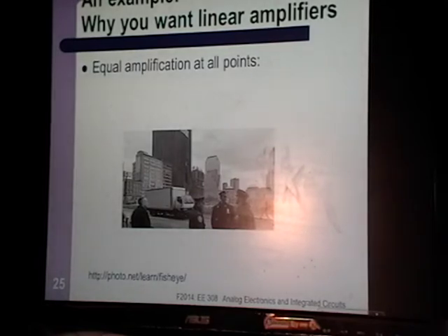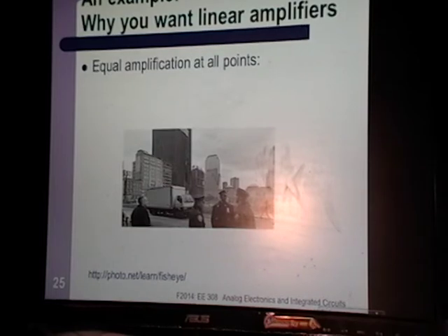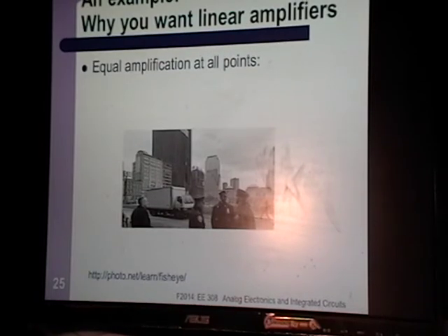All right, so we talked about linear amplifiers. Okay, let's go back to operational amplifiers. In the definition of operational amplifiers, all it says is the gain has to be big. It doesn't say anything about linear. And it turns out you don't really care. As long as the gain is big, you don't care if your operational amplifier is linear. But there are cases where you want a linear amplifier.